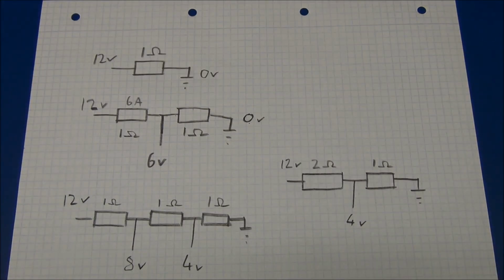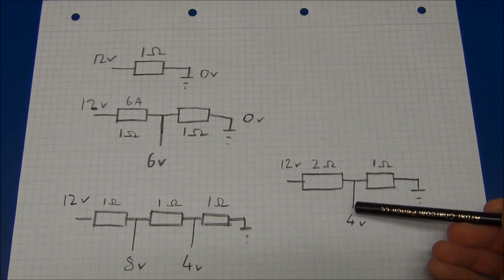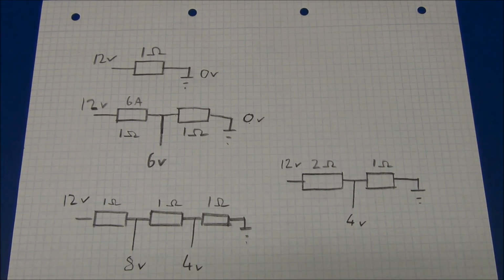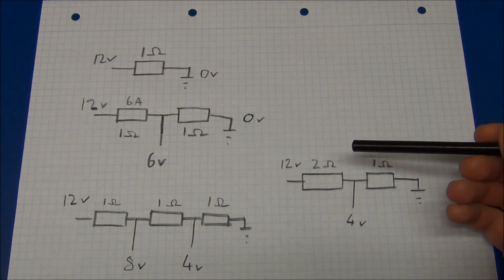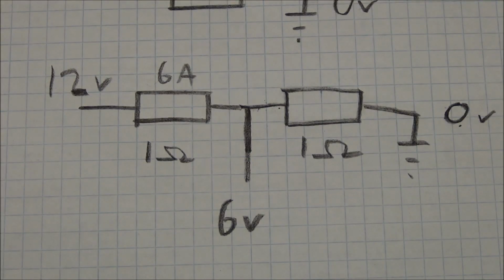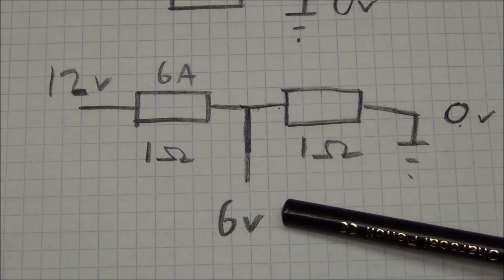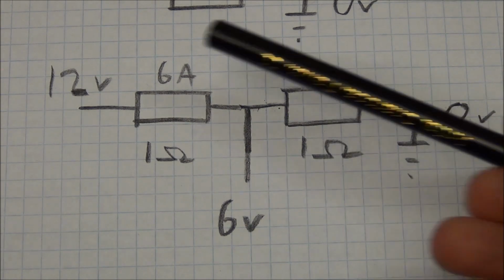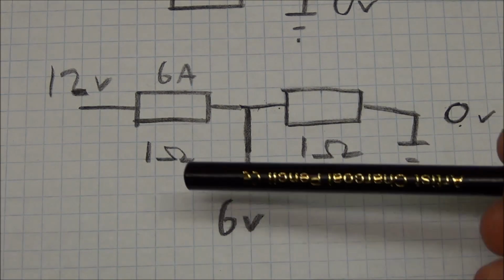voltage. The only disadvantage with this is that you cannot draw any current from this node. That will affect the output voltage. And of course you probably would not use 2 and 1 ohms, because that will draw huge amounts of current. So it is actually very easy to understand why this voltage will change once you know the theory behind how the voltage divider works.